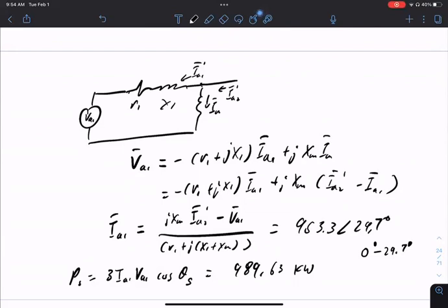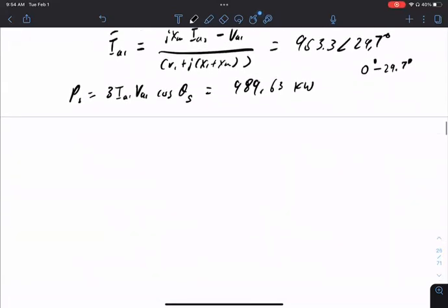So there's a lot we can do. This question really shows all the things you can compute, so this is a good example to remember and study. I can compute the power losses. I can compute the slip power. And the one thing you want to know is the injected power: is it flowing from the grid to the rotor, or from the rotor to the grid? That we have not answered. I have computed the developed power, and I have computed the power out of the stator. The question is, what is PR, the injected power? Is that positive or negative? Which way is it going?